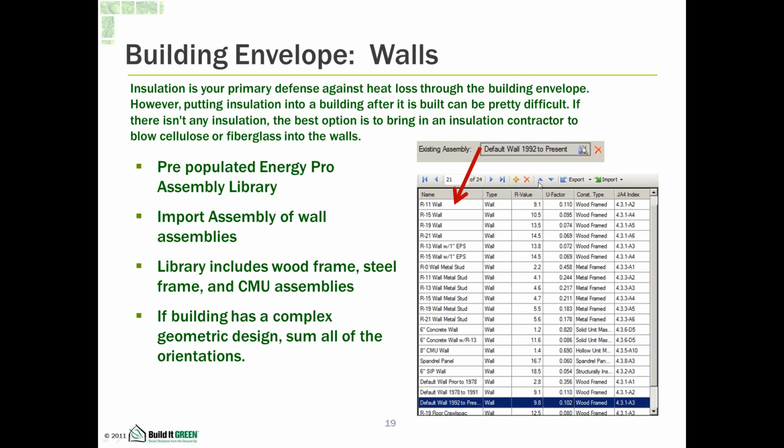But the only caveat when you import is you have to use a little yellow plus button here, which adds a new assembly. You're going to have to rename that and then import that renamed assembly, because this add just copies whatever you have clicked.